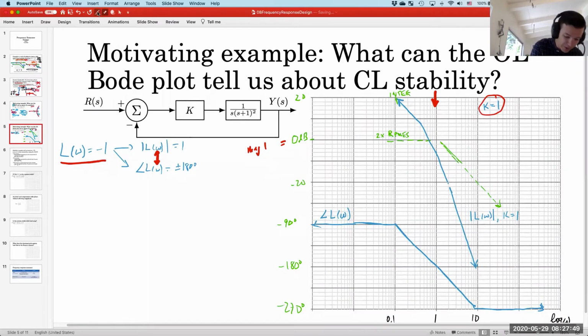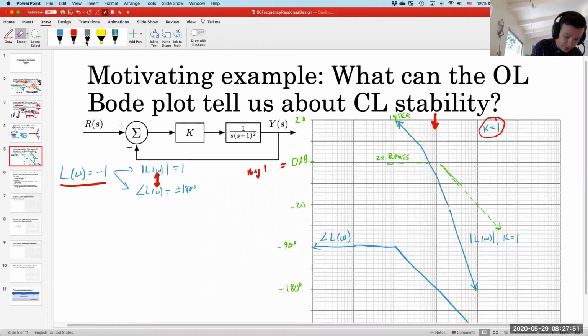Okay, so one more time for those of you who didn't catch that the first go round. Each of these poles should be minus 3 dBs at 1 radian per second. But since there are 2 of them, then we get down to 6 dBs below.